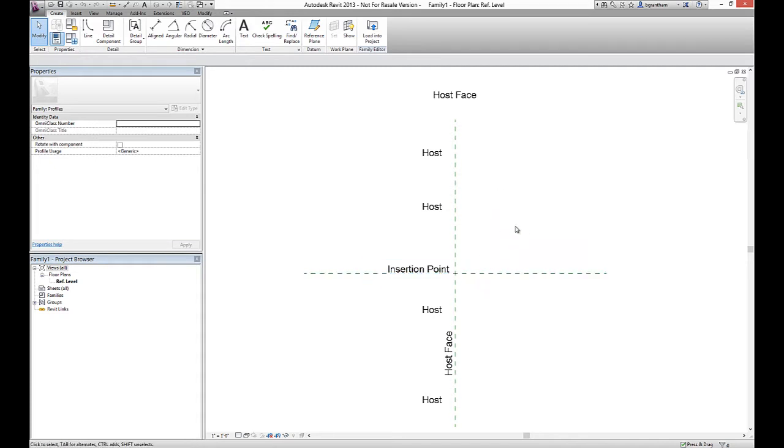The insertion point tells me at what point I will be managing this object. If we're dealing with an object that is going to be to the center, we're going to dimension to the center point, so we'll want to make sure that we conduct that object between the center line here. The other part of this is that if we want something that's going to be hosted to a top or to the base of a wall, we'll want to utilize those respective pieces. To the top, we'll probably go to the top of a profile here. If we're going to utilize a base, we'll use the base going up from this line here. In this case, we're going to be doing a base.